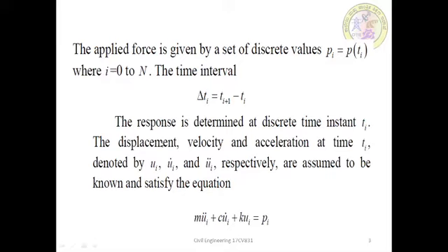The response is determined at discrete time instants t i. The displacement u i, velocity u i dot, and acceleration u i double dot at t i are assumed to be known, satisfying this equation.